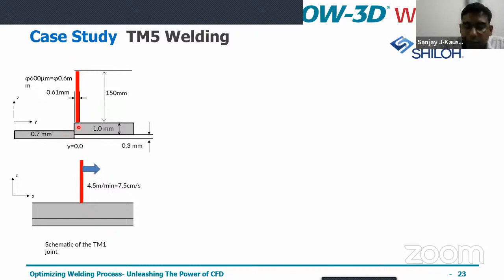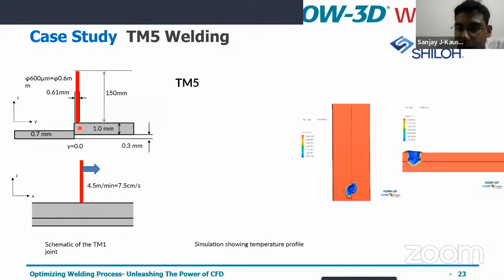This arrangement of the plates is quite different from the first one, and they applied the same laser power to it, and they see what kind of defects there are or how the solidification is taking place here. Here you can see one kind of defect, that is burn through. What is basically happening is the welding is completely and deeply penetrating through the weld and it is moving forward.